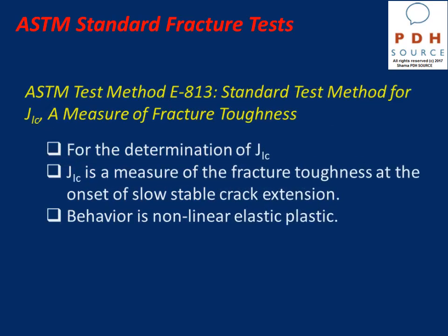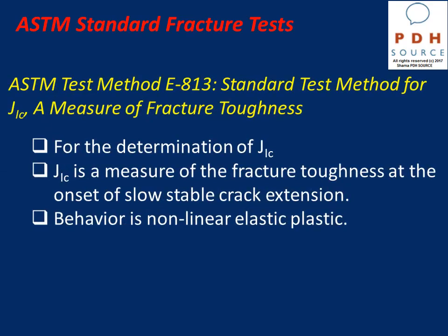The next test is ASTM test method E-813, standard test method for J1C, a measure of fracture toughness, and this test is basically for the determination of J1C.